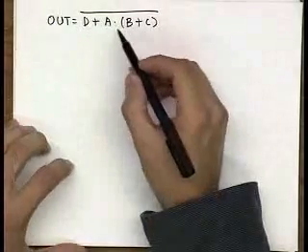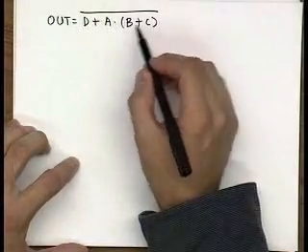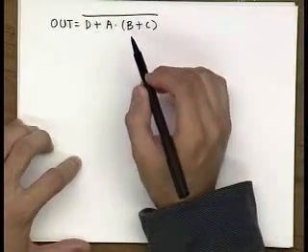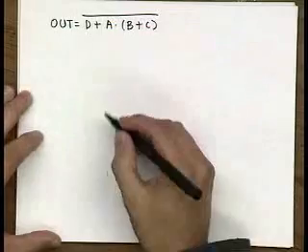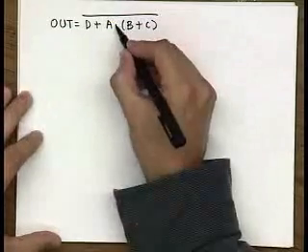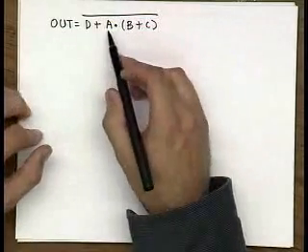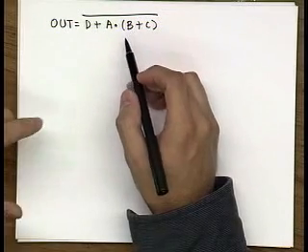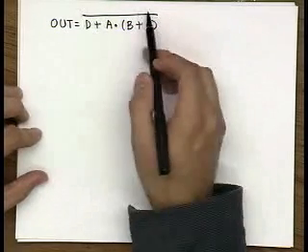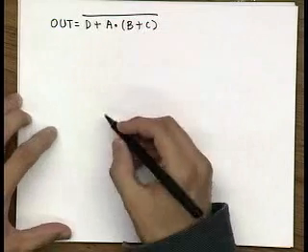What you know is that AND is a serial combination of NMOS transistors. So let's first implement the pull-down. We know two fundamental principles here: AND is a serial combination, OR is a parallel combination. And since we are passing logic 0, that's why we have this complement here.